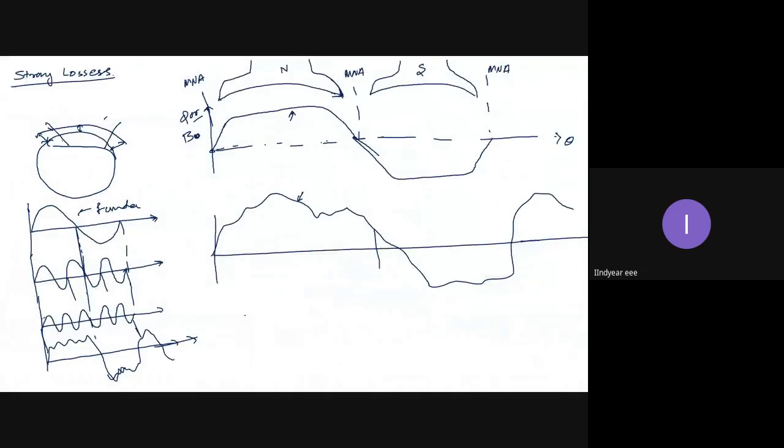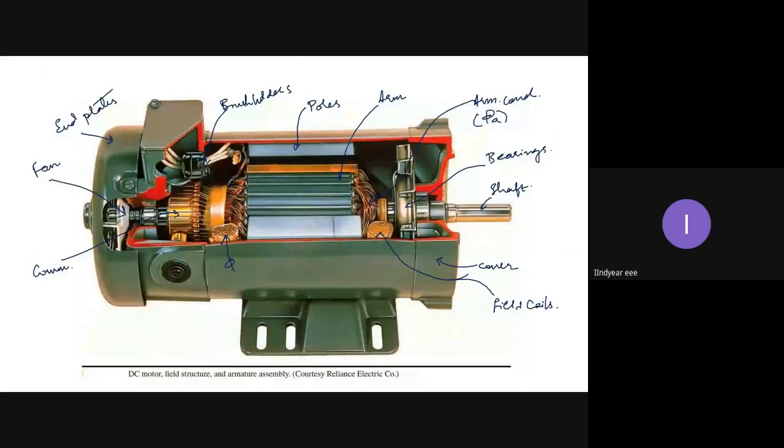Now, this is the resultant waveform. This is called a harmonically affected wave. Now, the same thing happens with the flux wave in the DC motor when the armature conductor starts carrying current. Because the DC motor flux wave is not uniform, the EMF induced in the armature conductors is not sinusoidal. Therefore, the current flowing in the armature conductor is non-sinusoidal. That is, the current produced is harmonically affected.